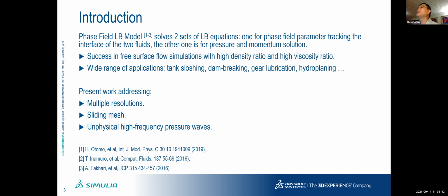There are a wide range of applications of these models, such as tank sloshing, dam breaking, gear lubrication, hydroplaning. The present work will address multi-resolution sliding mesh and removal of some unphysical pressure oscillations.